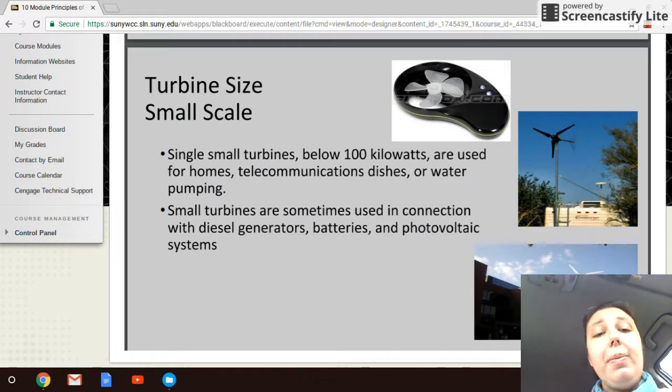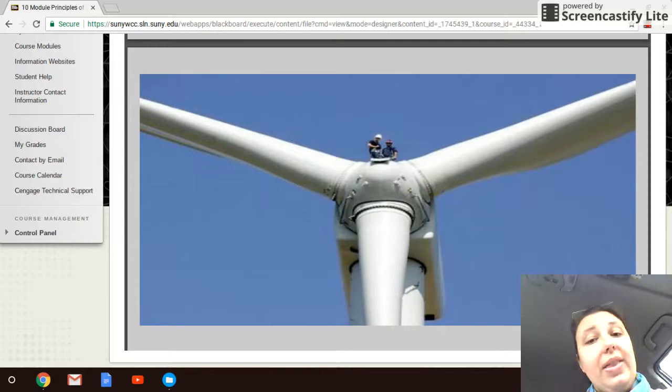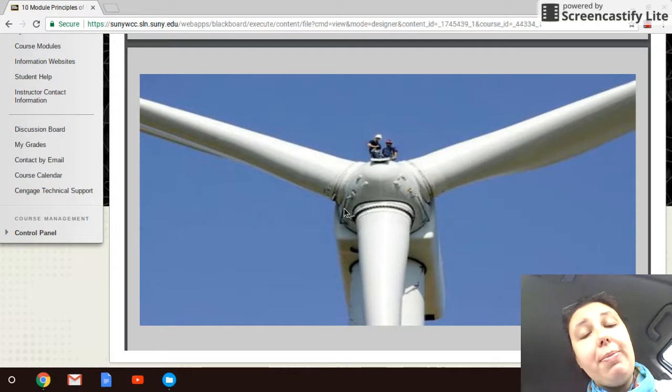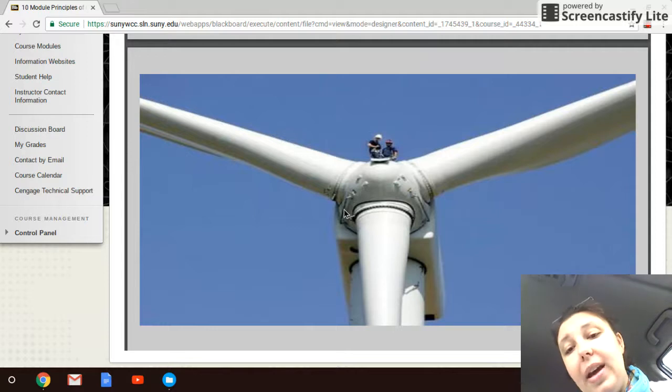To take the flip side of that, once again, really quick, popping back, the big scale stuff are the ones that are going to have yaw drives and anemometers. They are going to be upwind, so the wind is coming over the front of the rotor and sliding over the back of the nacelle. The blades can pitch. You can actually see the gear structure on the blades so that they can pitch to maximize the potential for rotation. And so these systems are much more complicated.